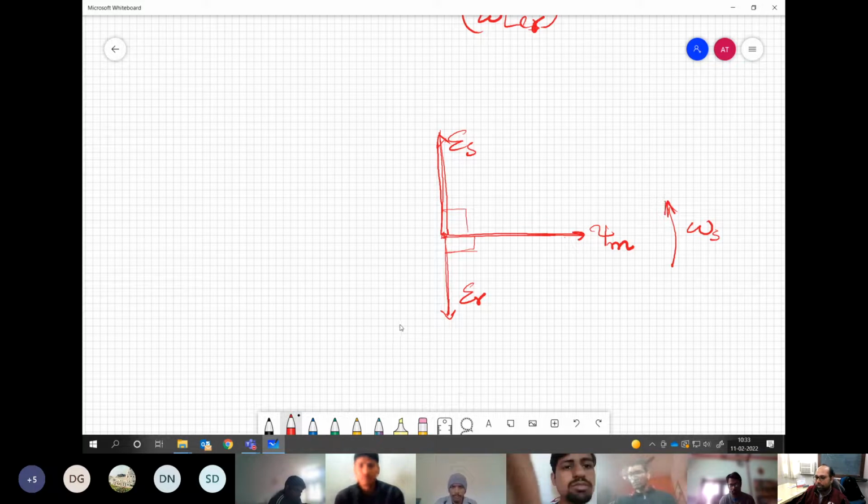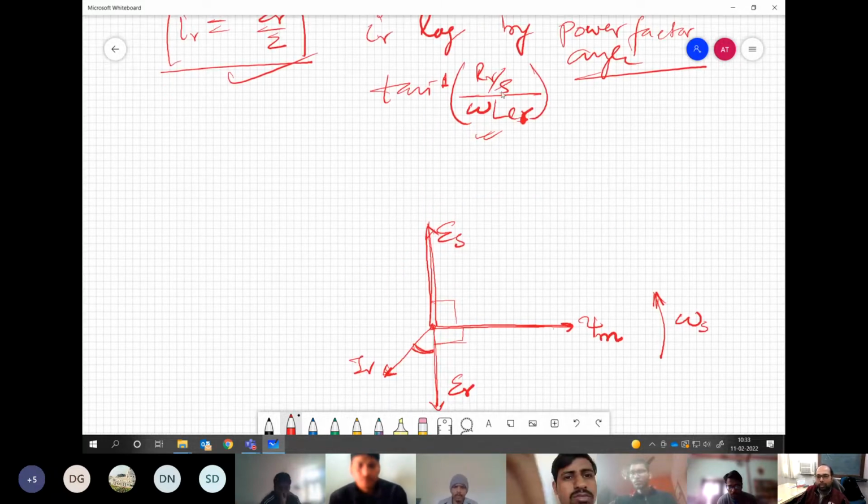Getting my point? Yes, sir. And then you have your IR, which is at some angle with respect to ER, as I just said. And most of the time, the slip value will be very small, right? So this angle will be very, very close to 0 degrees.